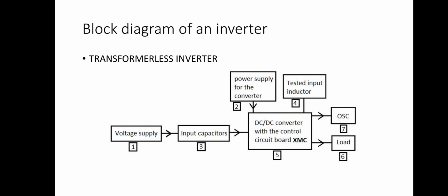So it will boost this battery voltage, so that when the H bridge is supplied with that 440 volt or 400 volt or 330 volt, it will switch in between. Now there will be a feedback that will go back to the DC to DC power supply, so that it will maintain the particular voltage until the battery drops down. If it is 220, it maintains 220. For Americans that use 110, it will maintain 110, and for Germany 250, it maintains 250.